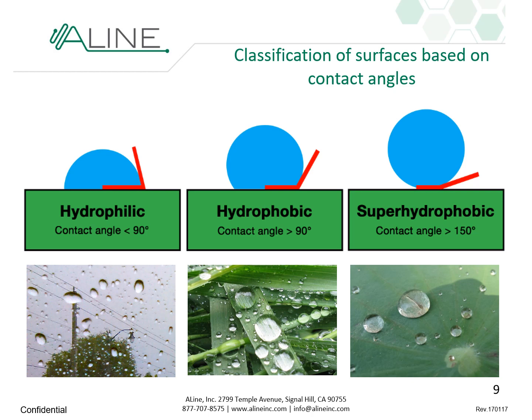This contact angle measurement is really important because it allows us to classify surfaces depending on their wetting properties. If the contact angle is below 90 degrees, a surface is typically defined as hydrophilic. Water will tend to spread on it, and the droplet shape would be what you probably expect from a standard windshield of your car, with the droplet streaking and creating a larger surface area.